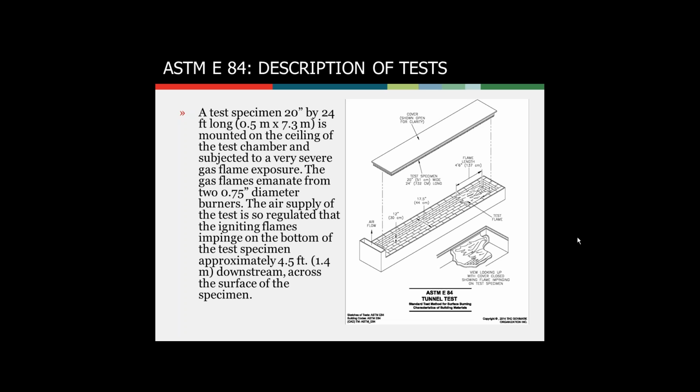Once that's finished, you pull the sample out, cut it to the lengths for the test, and then test the material. Of course, you have to condition it afterwards. So it's put into the forced draft oven for the specified amount of time in the NFPA 701.